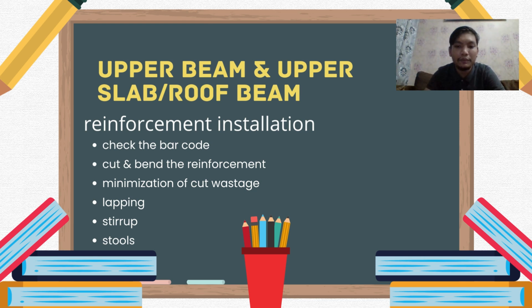Then, stirrup. Stirrup will be required at areas of high shear such as a bearing point and below large point loads. And then stools. Stools are used to separate the top reinforcement mesh and bottom reinforcement mesh. It is mostly used on slab.